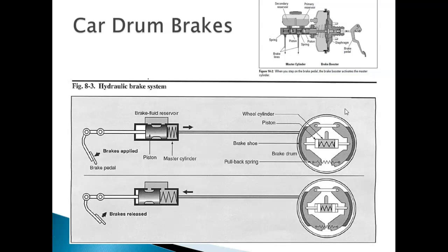By the way, what do you have to do every time you work on your brakes? You have to bleed them, because what do you generally introduce whenever you are starting to work on your brakes? Air. What do you not want in your brake system? Ever. And I mean never ever.